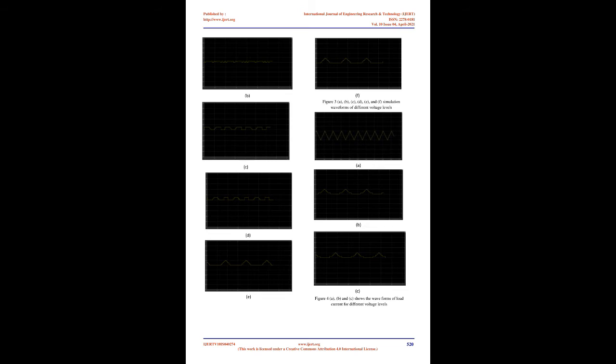G. Lefebvre et al. have proposed a multilevel flying capacitor boost converter. It is analyzed for asymmetric voltage operation. This permits loss optimization that takes advantage of different voltage class MOSFETs. A cost-motivated design of a suitable zero-voltage zero-current switching snubber is then developed that permits a great reduction of the inductor size.